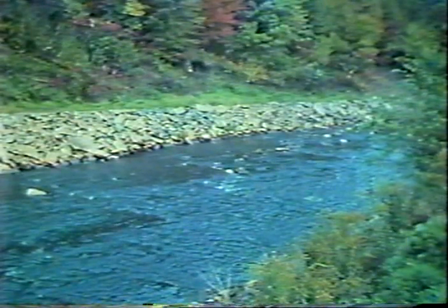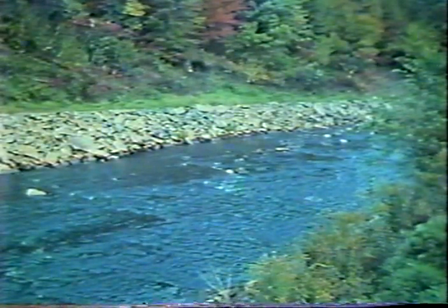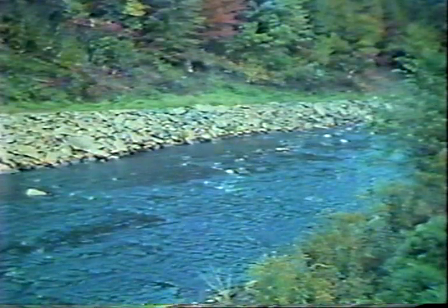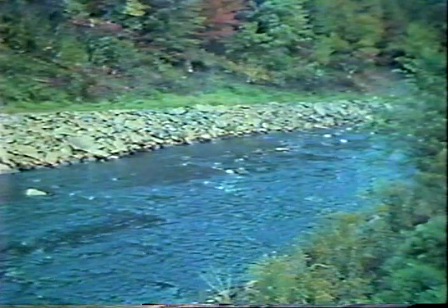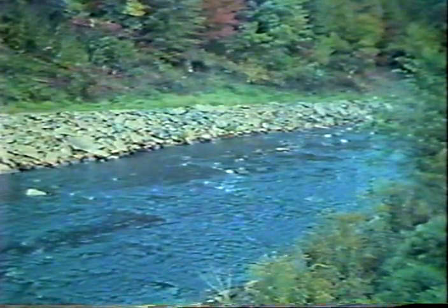Dumped rock riprap is a proved countermeasure for protecting stream banks and bridge abutments when applied according to established guidelines. In many states, however, riprap of good quality is prohibitively expensive because it must be hauled for long distances. Concrete slope pavement is a satisfactory countermeasure for erosion of abutment fill slopes if it is protected from undermining at the toe and ends, either by a cut-off wall or by riprap, and is properly designed to resist hydrostatic pressure.